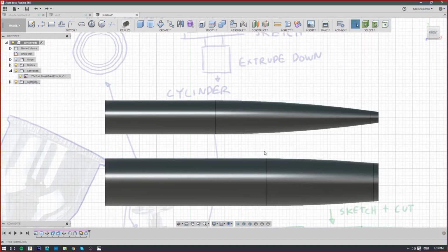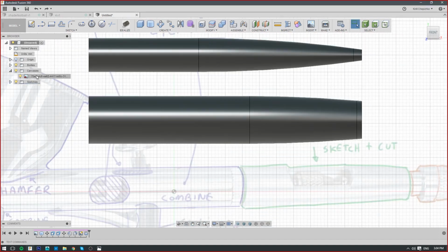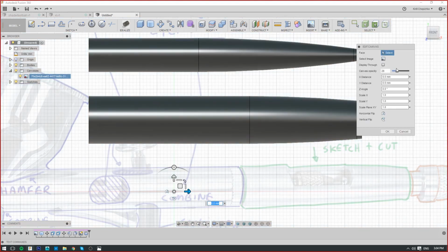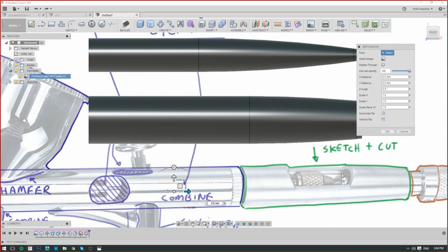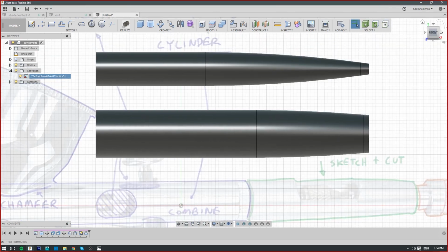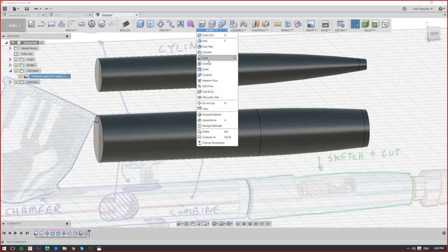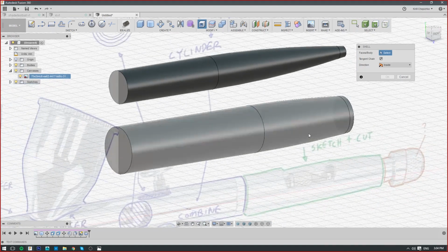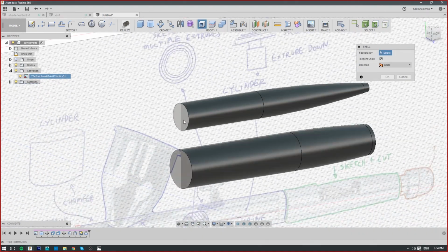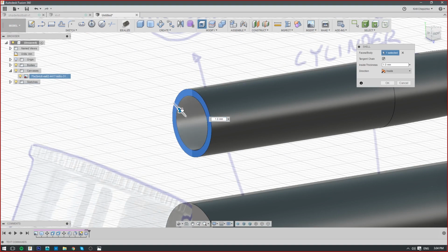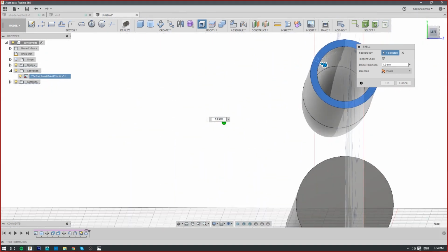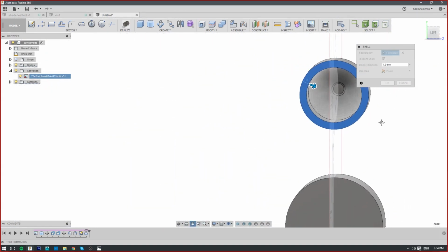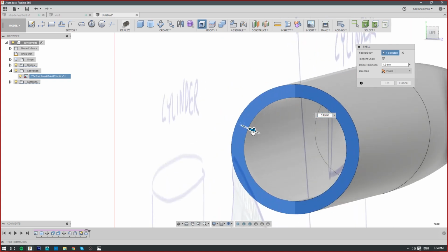Now from here we have this, let's bring the opacity back. Oh, we have this nice cutout that also indicates that our cylinder is hollow inside and it has some thickness, right? Yeah. So that just means that we need to use shell, for example, from this face. It basically empties out the object like that, and then you control that thickness.